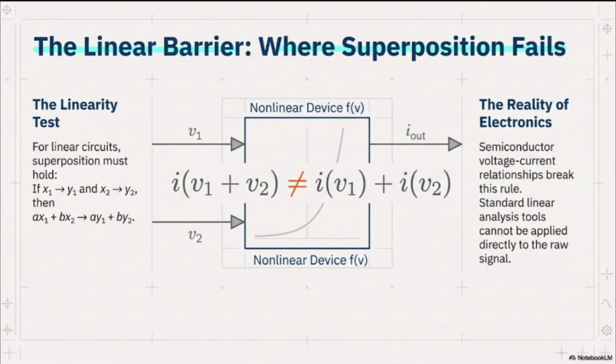As you just know, superposition was one of the methods that we use in order to handle our circuit. It means that when I have two sources at a time, for example V1 and V2, and I'm looking for the current that goes inside the middle branch, for example, I call that I1, I could consider only V1, get rid of V2, and find a current. In the next part, I can get rid of V1, consider V2, and find another current. And the final step, the only thing I had to do was to add those currents that I found.